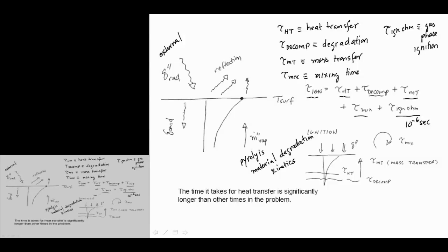So our time scale for mixing looks like a length scale divided by the characteristic convective velocity. So let me just put that here. It looks like some characteristic length scale divided by some characteristic velocity. So if we're talking about maybe a sample on centimeter length scales, so 10 to the minus 2 meters, and our convective velocities are comparable, U characteristic, we said centimeter per second, so similar. So all of a sudden, tau mix looks like, say, 1 second type scale.